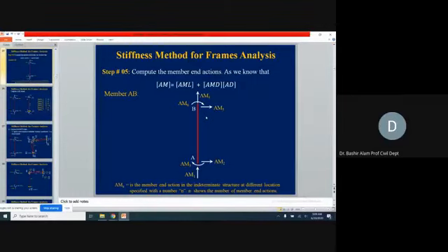And I'm coming to a specific end now. Let's say A is my near end, the starting end. So vertical, followed by horizontal, followed by the moment. This is my labeling sequence: AM1, AM2, AM3. First I assume my positive directions, upward, rightward, and clockwise.